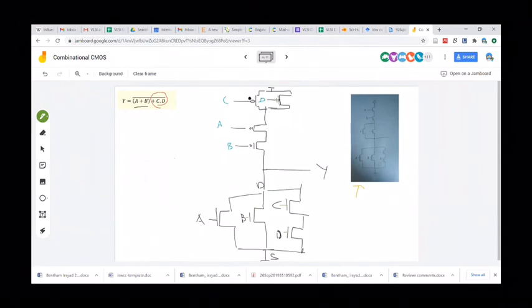Even the drawing inside the picture, there's no bubble for PMOS, so you have to add a bubble here. You need to be careful because they're PMOS. And that source should be connected to VDD. Okay, good.